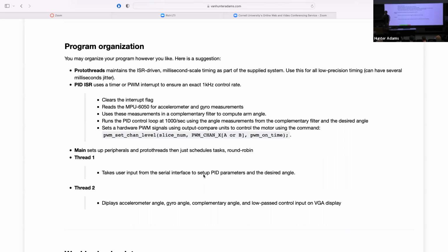Mahmoud had a good idea, which was on the controller output, wouldn't it be interesting to plot the proportional contribution to the controller, the integrator contribution to the controller, and the derivative contribution to the controller, in addition to the sum total of the three, which is the ultimate output of the controller, for debugging purposes.